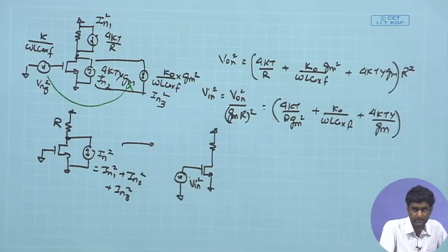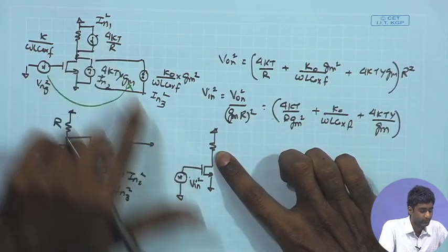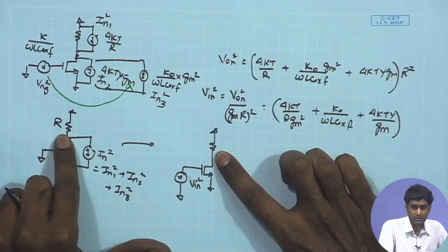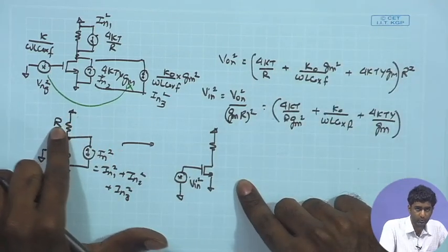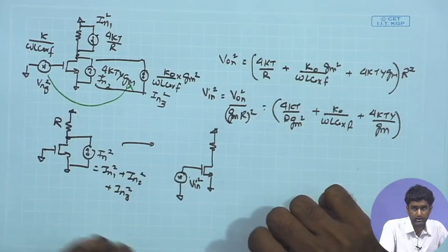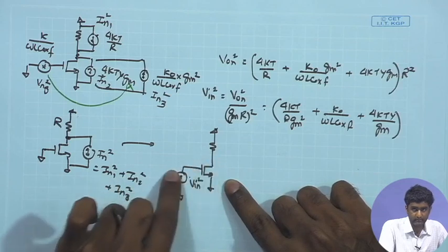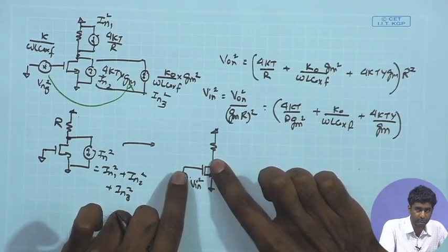And the reason is that this R term, although it is contributing to a mean square value given by 4 kTR, RMS value root under R, the input signal is getting magnified by R. So, the magnification for the input signal is proportional to R.